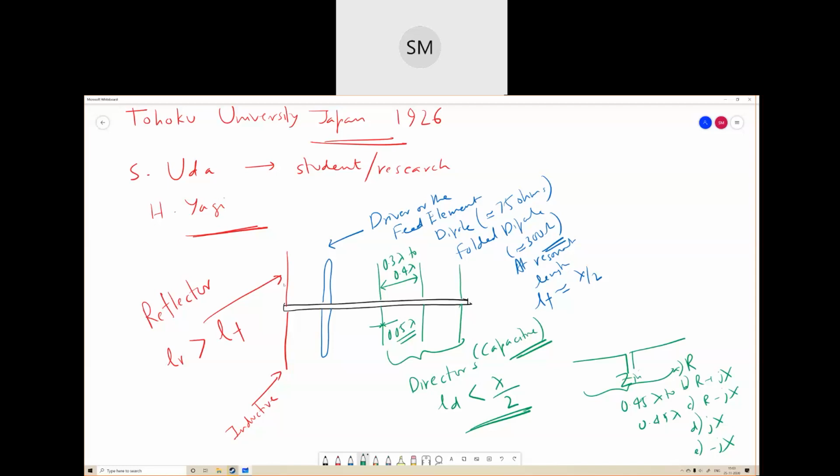So think in this way. This is an inductor where the current is lagging. This is a resistor where the current and voltage are in the same phase, and these are capacitors where the current is leading the voltage. So think of it this way, there is a phase change, a phase lead. If this phase angle is 0, this phase angle will be alpha 1, this will be alpha 2, this will be alpha 3, and this is alpha 4. So can we write this?